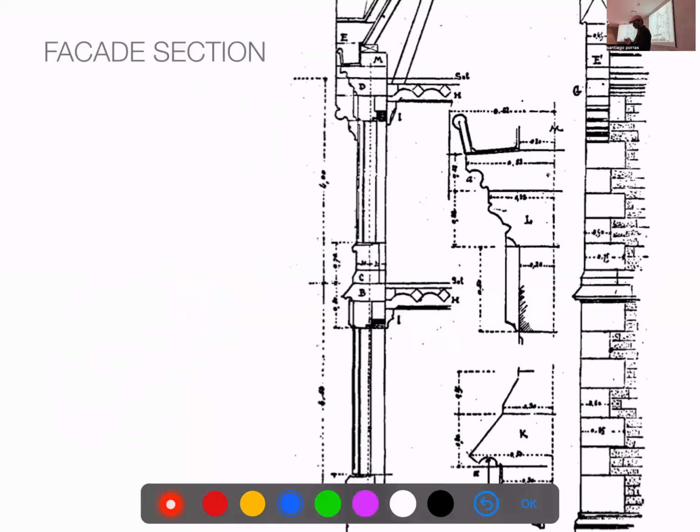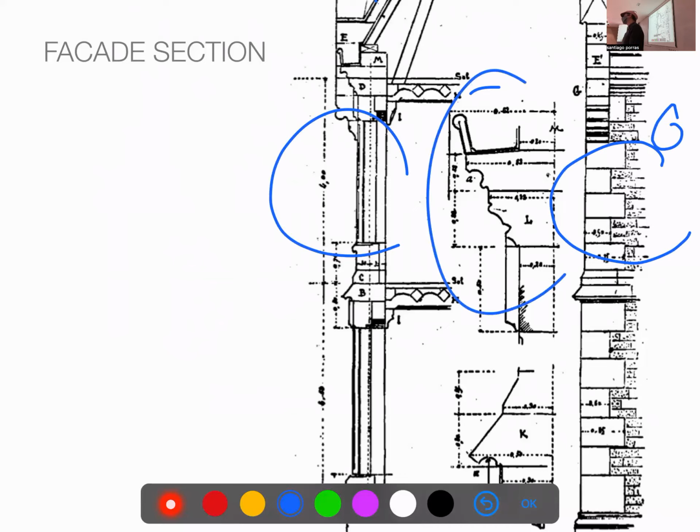And then the section. See, we have a full facade, full elevation, and we have a full section of the facade. And then we can go into the details: the corner, of course, the windows with the roof, the plinth, and the details. Always you have to use the 3 scales: full building, section, and the details. You have the context. Because if you have only this detail, it's very hard to understand how it works, the logic, and how it integrates in the building. So basic dimensions.